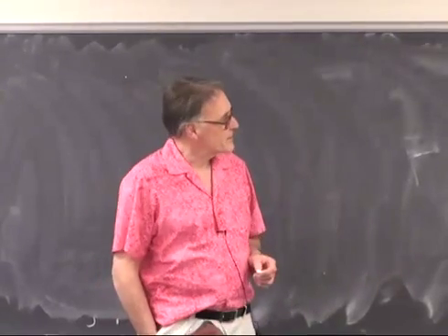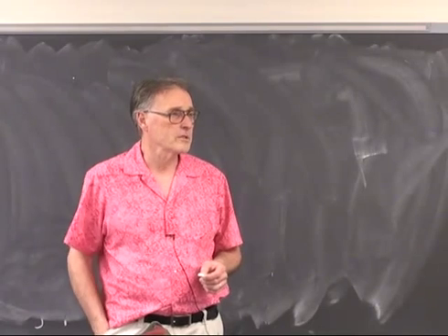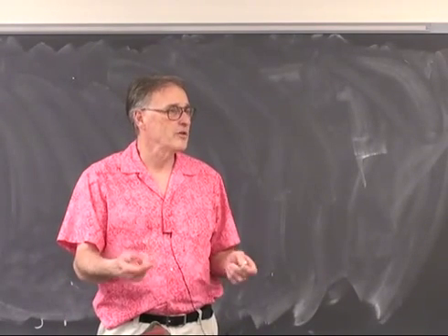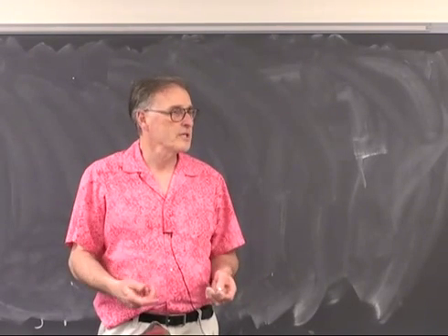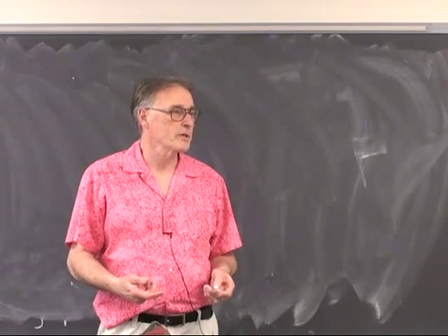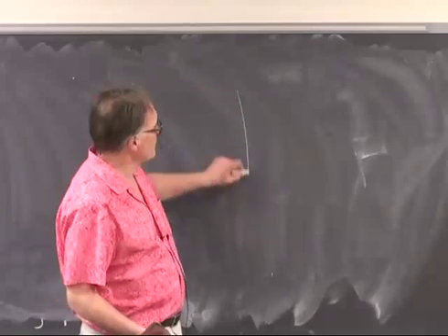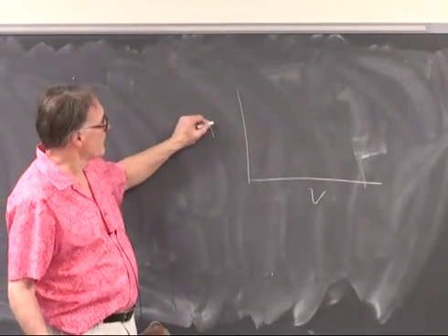Yeah, I like it. So you could use voltage dividers off of the 5 volts into separate port pins. Let's say A2, A3, and A4. So you'd have known precision voltages into those ports, and then you could absolutely do a 2-point calibration. The way you do a 2-point calibration is V versus number.